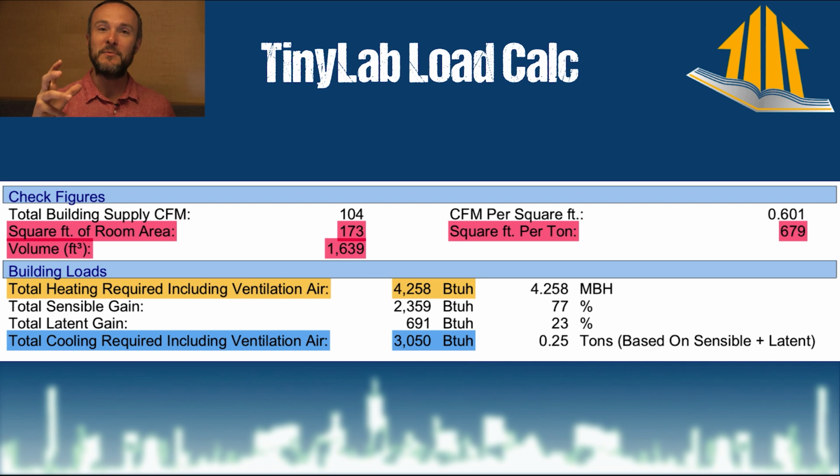So I've got a system that's already double oversized. If I keep on insulating this place and make it more efficient, I'm still gonna have to buy the same tiny piece of equipment, which is the smallest one they make in the world. So there's a little bit of the experience. You can use the software, but you have to understand what it means in real life